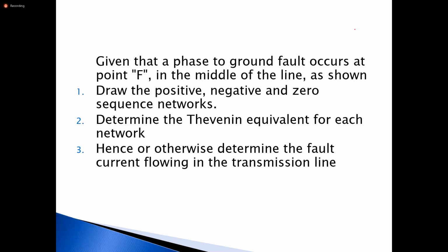All right, so given all of this, where do we go from here? We go back to the steps. The first step is that we need to draw the equivalent circuits. I want to replace each component by its symmetrical equivalent and then form the per unit networks, positive, negative, and zero sequence networks.